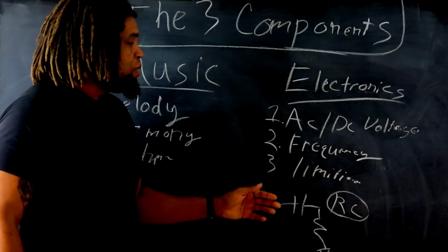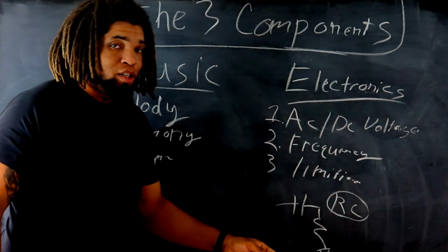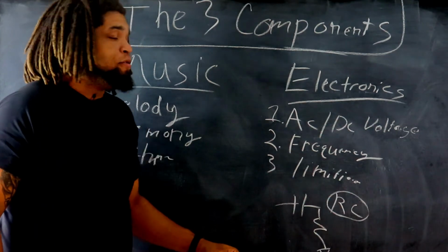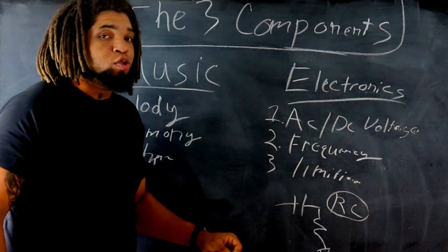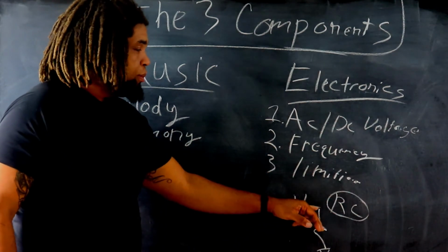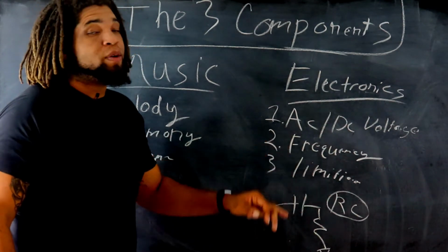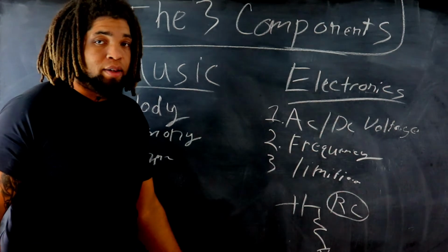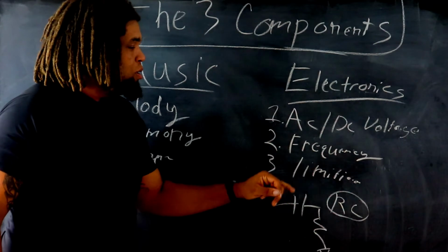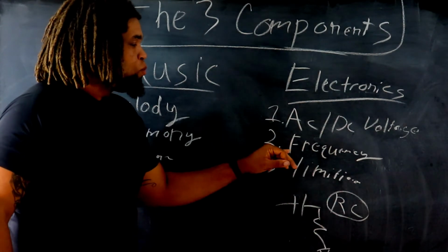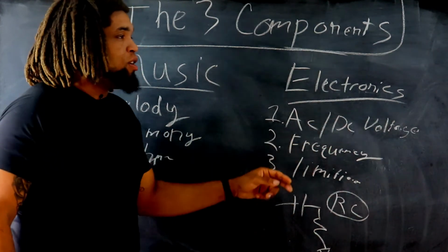Let's say, for example, if I want to eliminate the passage of DC voltage going to a certain area of the circuit, I have to keep in mind that this capacitor that I'll use to block that DC will also attenuate the frequency in some way. So I have to manage my DC voltage attenuation with the frequency as well, because these two things can change simultaneously.